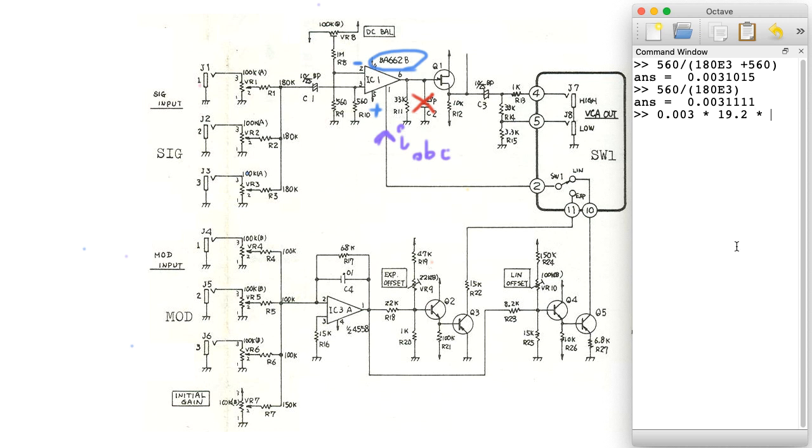Now we need to turn it back into a voltage. That's what the 33K resistor does. So it's all of these numbers times whatever the control current is. So let me just go ahead and compute that. So I'm getting 1900.8. Let's see, what does it look like if I actually put in the more detailed numbers that I had above? It does look different. What if I did something like this?